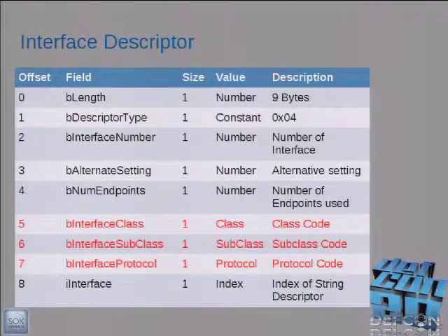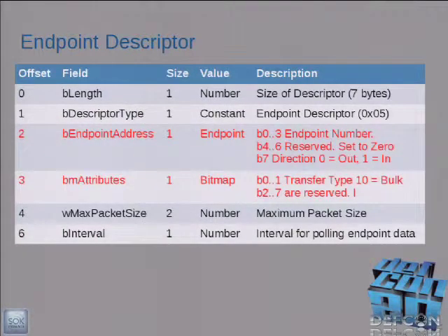And again, in the interface descriptor, we can have the class, subclass, and protocol. If we had zeros in the earlier descriptors, then we eventually do have to say what kind of device this is. And then we have to describe our endpoints. In the case of a mass storage device, as I'll say in a little bit, you're going to have at least 3 endpoints: the control endpoint, bulk in, bulk out.